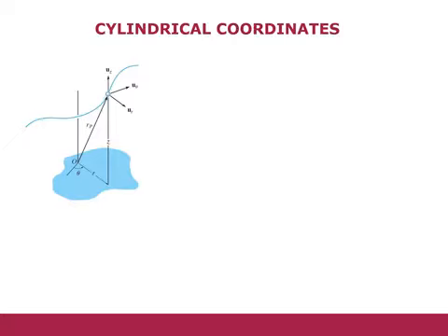So we can represent the position, velocity and acceleration in terms of these coordinate systems to analyze the motion of our curvilinear motion. As we have studied, in the rectangular coordinate system the velocity can be represented in x, y, z. For example, we can represent our velocity as vx i plus vy j plus vz k, where i is the unit vector and vx is the magnitude. Similarly, we can represent the position and velocity in terms of the cylindrical coordinate system.